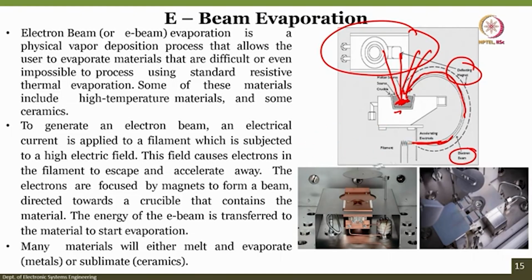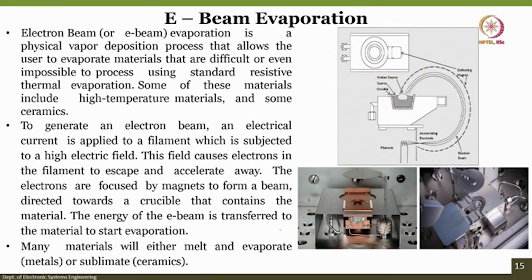Now, if you see the second schematic here, you can see how you can block the evaporation until you feel there is uniformity of the melting material. Here also you can see the same thing. When the material starts evaporating you can remove this plate from the evaporation site, and then you can deposit the material.